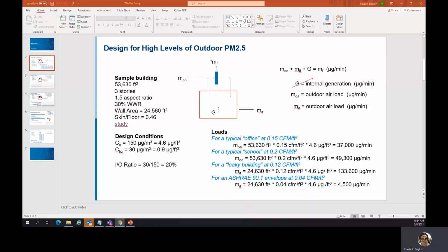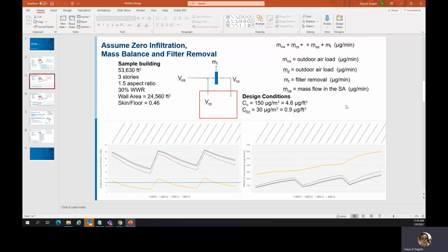So the primary tool for removal is the filters. Let's take a look at filters and just look at how some of the math works around filters. Basically, all the air hitting the filter has the removal effect of the filter. And so in that sense, return air is important as well as outside air in order to create a removal effect. One way to improve or increase the amount of removal that's happening at the filters is to increase the overall flow through the filters.